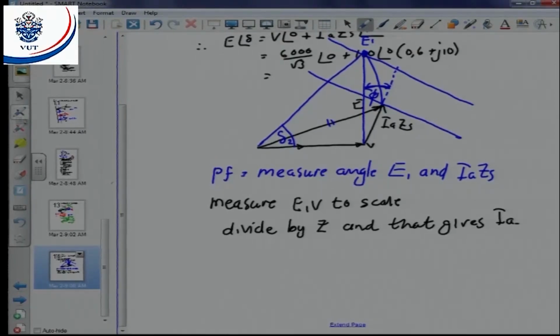Now the second part of the question is determine the armature current and power factor if the power remains at 200% and the excitation is increased by 1.2 per unit. So now, as E becomes longer, it will move downwards until such point that it touches the line 2 per unit, and therefore that is the case. Let's say that is E2.